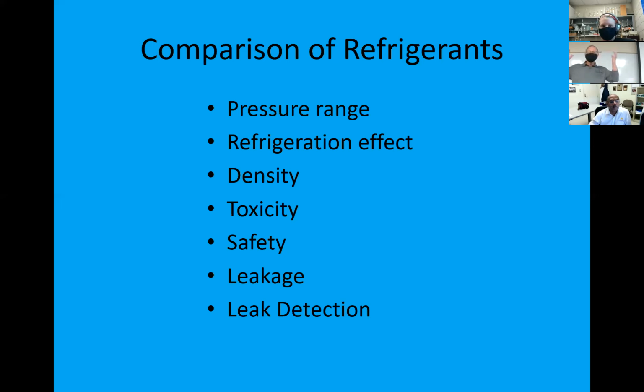So if we were trying to refrigerate this in Minnesota, we don't have that restriction because we were allowed to replace our ammonia system when we broke down back in the 80s. But again, we replaced just a small portion. As we bought new equipment, we switched over to a different cooling system. Our freezers upstairs, our walk-in freezers and so forth, are not on an ammonia system. They're on the R502 system. So obviously leakage comes into play, how well something doesn't leak, and how do you detect leaks? You really need to be thinking about those types of things.